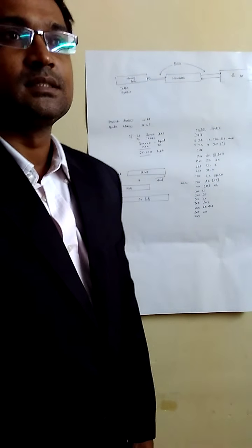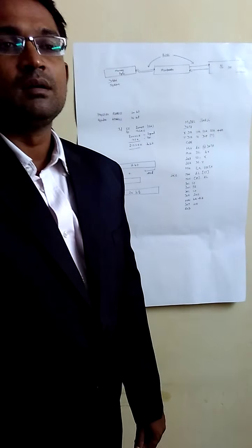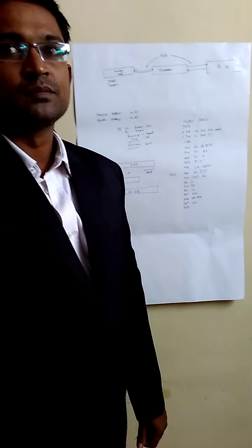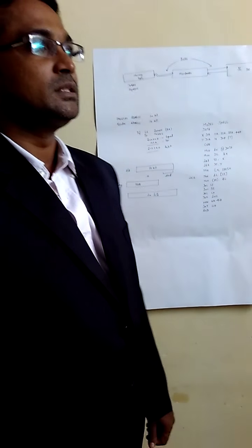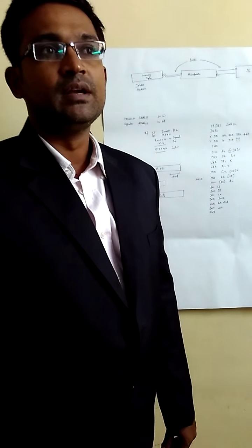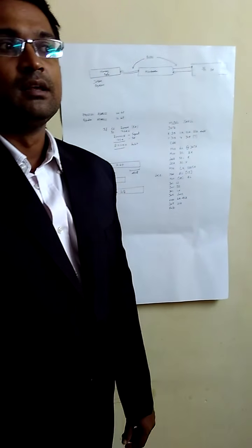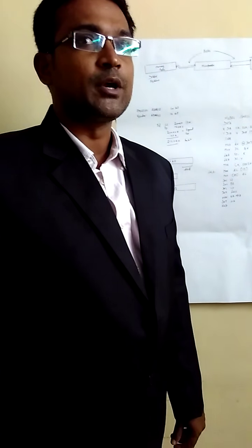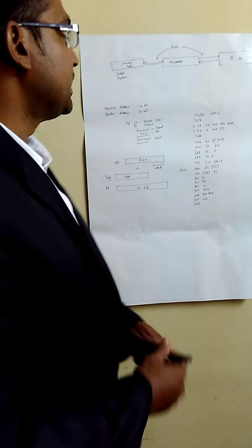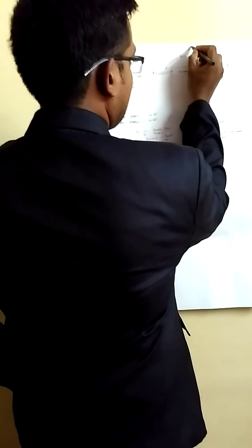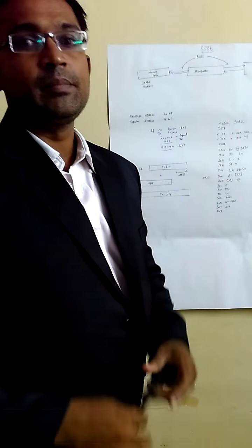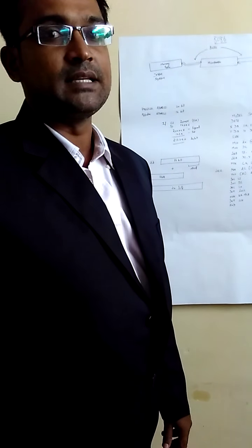Microprocessor is an IC which performs all arithmetic operations, addition, multiplication, subtraction, and other logical operations also. Now the microprocessor we are going to see is 8086. There are so many microprocessors like 8085, 8080, Zilog Z80. In that family, Intel developed a microprocessor of 40 pin IC, that is the 8086 microprocessor. It is a 40 pin IC having 16-bit data and 20-bit address lines.